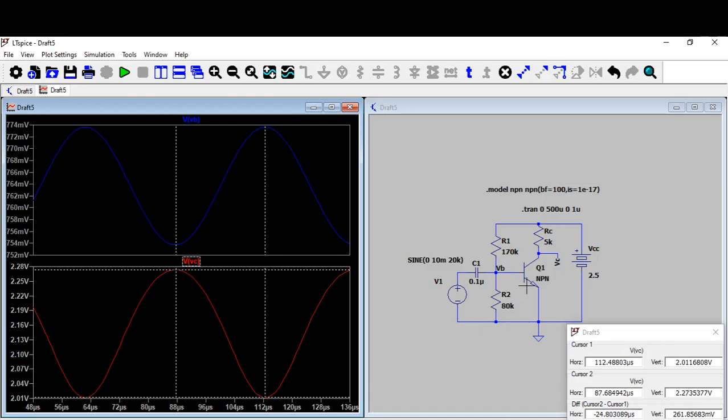Whatever values of R1, R2 and biasing conditions you have, for that biasing this circuit has to give a gain of 12 or close to 12 or 13, which is not too far away. That's what is called design of the amplifier. If the specification says that you want to get a gain of 25 or 50, I should be designing the circuit in such a way that it gives a gain of so and so.